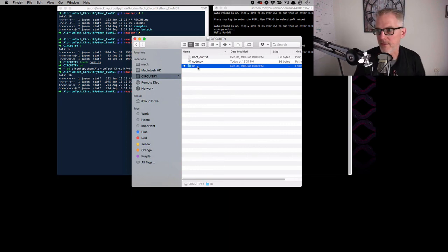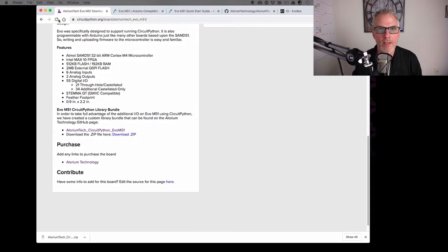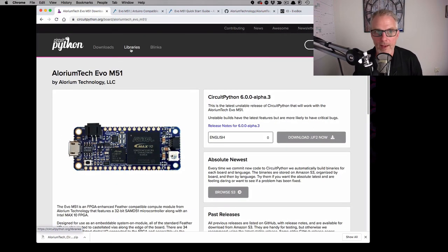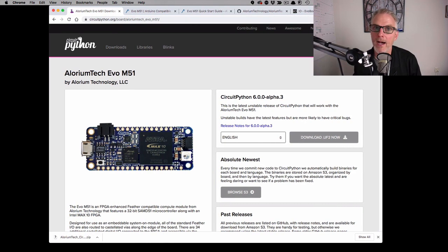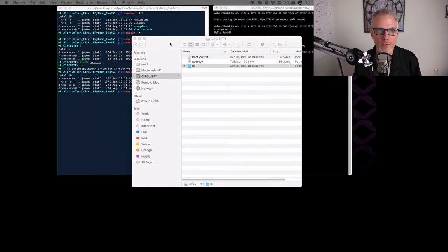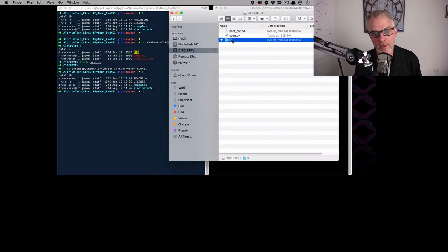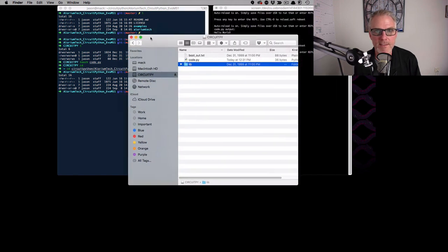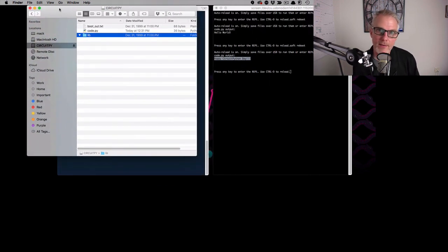And in fact, if you go to the CircuitPython.org page, there is a link specifically to go and find all of the libraries. So if you click that, you can get a bunch of libraries. And usually with any kind of example project, people are going to highlight what libraries you need. And it's fairly easy to go and find what you need. And in this lib directory is where you'll drop that stuff. In our case, we actually want to put the entirety of the Alorium folder into this lib directory.